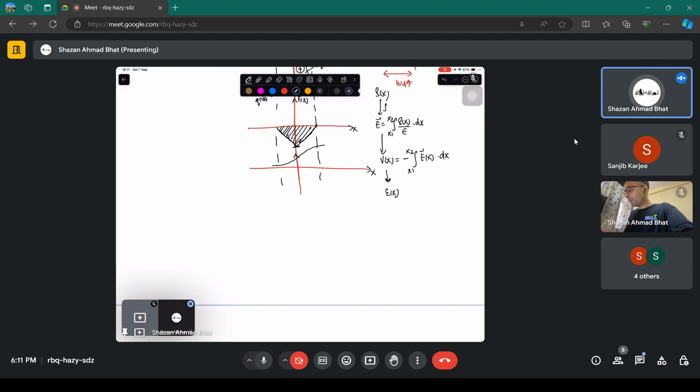Potential energy as a function of x is equivalent to minus q times V of x. So you have to negate it and multiply it with the electronic charge, and you get something like this. That's where the band bending actually comes from. So it's all coming from the simple electrostatic picture. So that's what you have already covered.